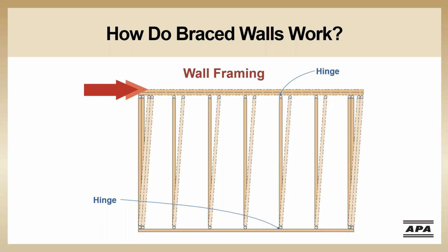Bracing can take several different forms in a wood frame structure. IRC section R602.10 on wall bracing has 16 different bracing methods. These methods include panel type products, let-in bracing, and portal frames. For simplicity, this webinar will assume a panel type bracing, such as wood structural panel wall sheathing, is used.